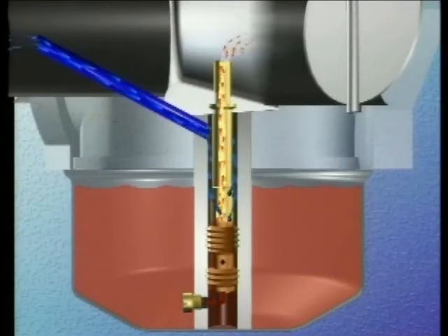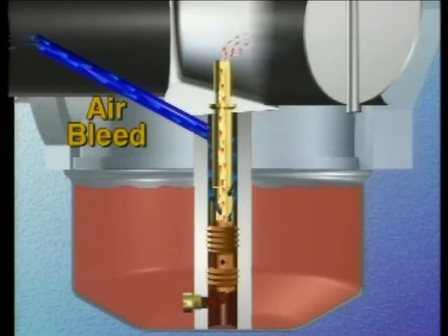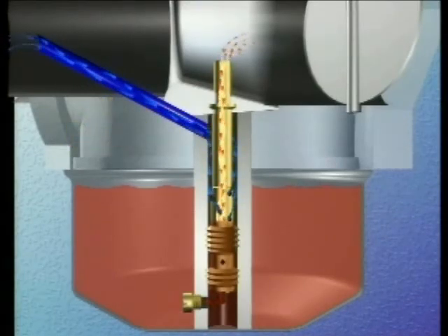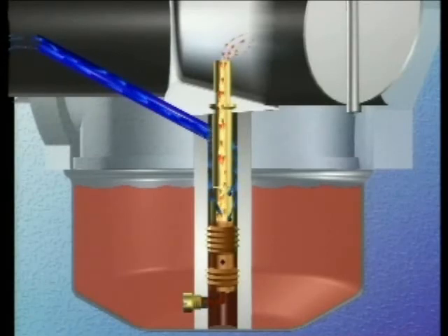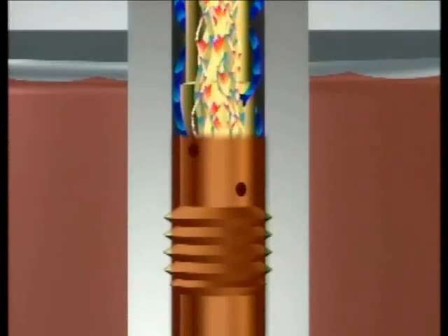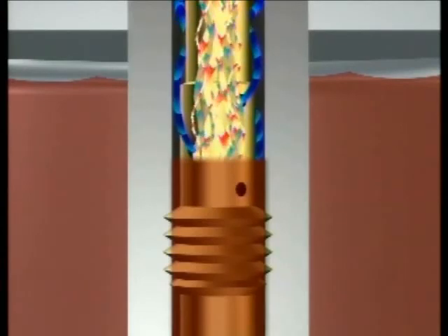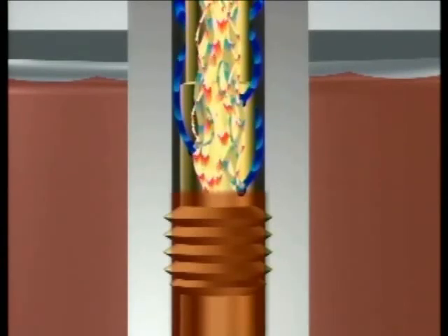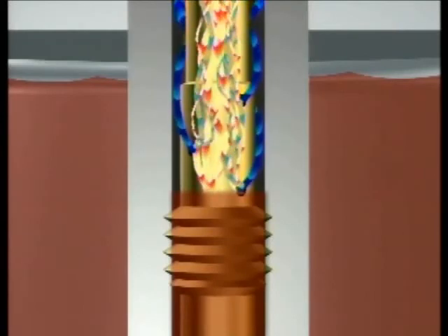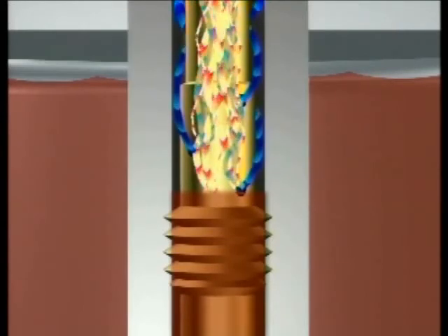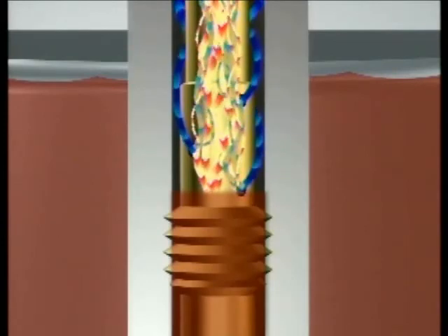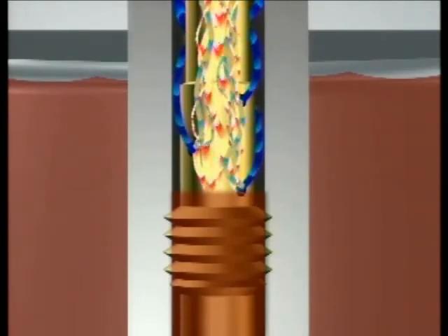At this point, the high-speed air bleed feature comes into play. The air bleed acts a lot like a bowl vent. It allows atmospheric pressure to act on the fuel in the emulsion well. With sustained pressure and airflow into the emulsion tube, fuel and air are forced up the tube and into the venturi. As the fuel level decreases, it exposes holes in the emulsion tube to the air entering from the air bleed. This allows more pathways for the air to get into the tube and start mixing, which speeds up the vaporization process and helps the engine run more efficiently.